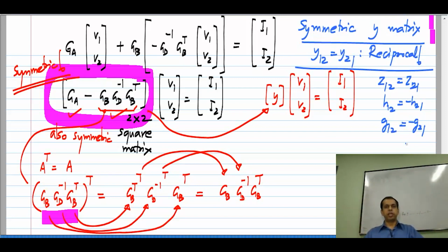So, using our knowledge of properties of the conductance matrix that appears in nodal analysis, we are able to prove that a resistive two-port network is reciprocal. Of course, we have restricted the kind of two-port networks. We have taken only a 3-terminal two-port network, but it can be generalized to arbitrary two-port networks, that is, 4-terminal two-port networks, in a very simple way.